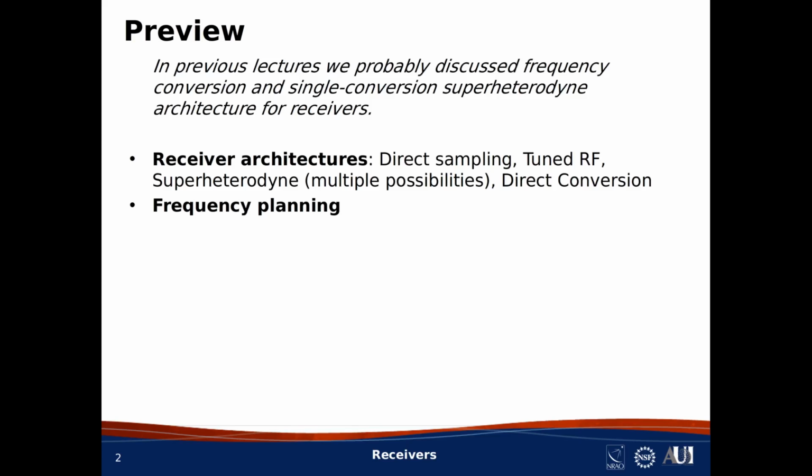As we go along, I'll introduce the concept of frequency planning. Whenever you have frequency conversion within a receiver, it brings up the question of frequency planning. That includes questions like, what will the local oscillator frequencies be? You may recall from the lesson on frequency conversion that low side and high side injection are options, and so these, among many other options, may be things that you need to consider. There are also lots of pitfalls, and one of these, for example, is the notorious half IF problem, and I'll briefly describe these problems.